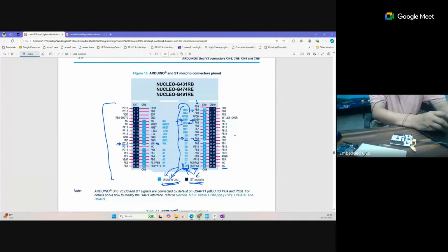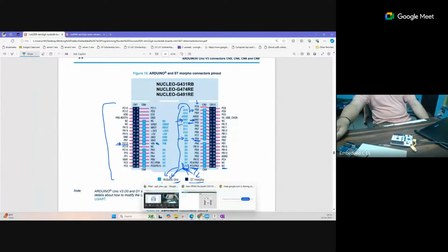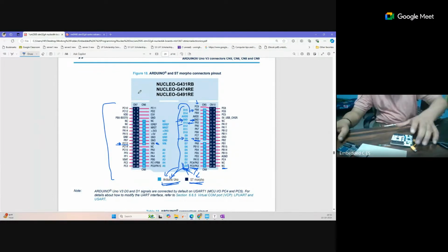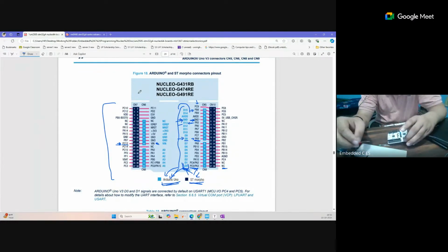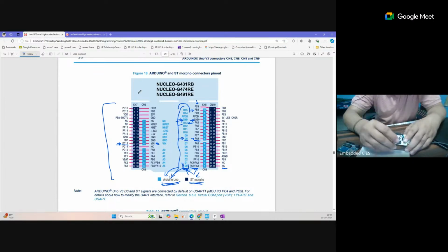Now let's configure this, or we can also use another pin. I'll also extend the code for this. We will use two LEDs and connect another pin also. Here I am using G and D for ground, and PA5, corresponding to the D13 pin, for the output. First, let's connect this. You can see on the board, I am taking the ground pin and connecting it on my breadboard.